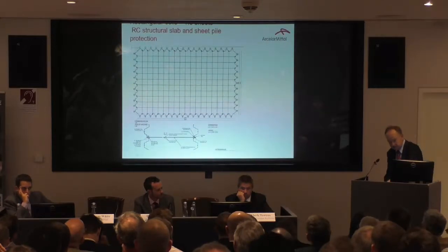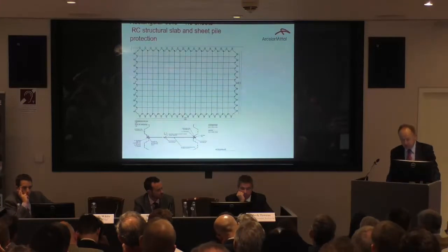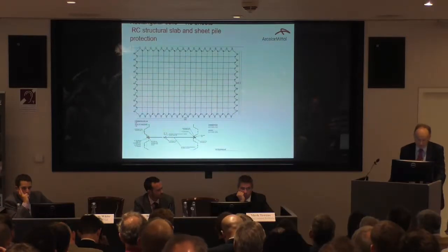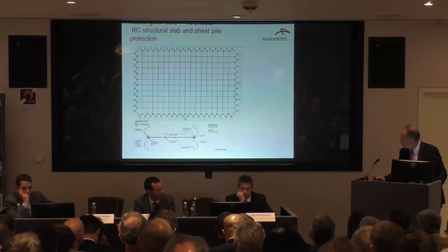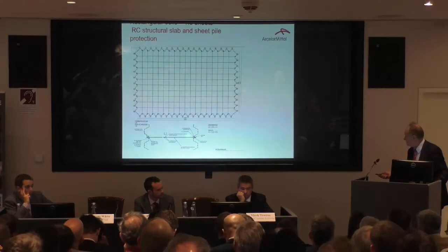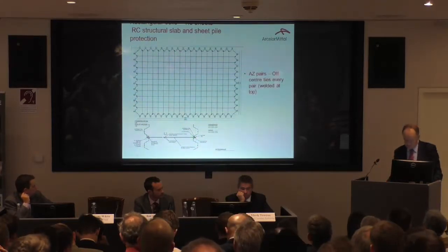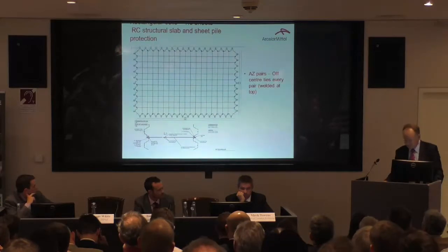So the particular details for the sheet piles, it's a good technique to tie all the pairs of sheet piles, in this case Z piles, together by off-center tie details, which we can find in the brochures. And actually weld the interlocks of the sheet piles at the top,